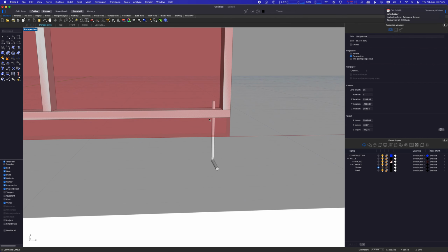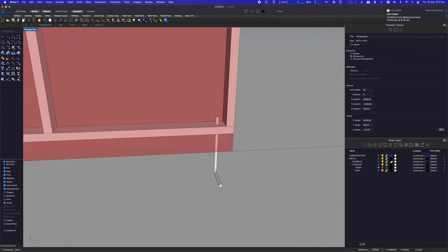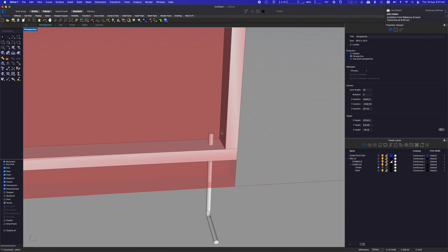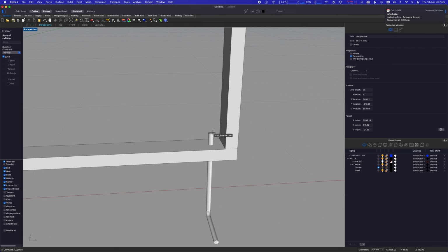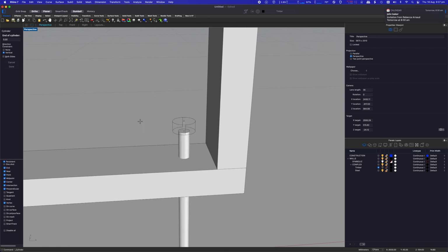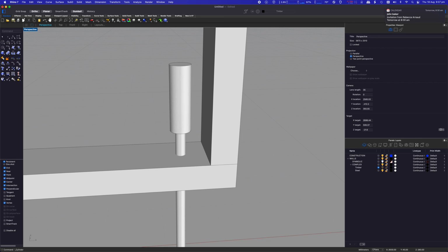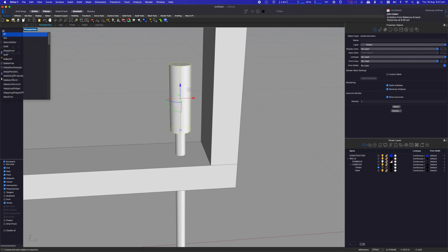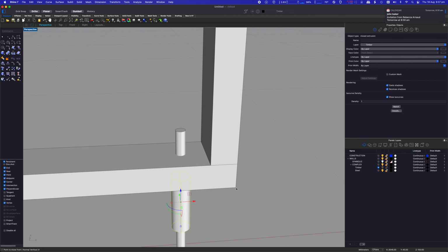So now we want the piece of 100 millimeter long 32 mil diameter tubing. So let's do a cylinder. Actually, let's just turn off the symbolic bit. Let's go from the center of there. We want, again, diameter 32, and we want it to be 100. Then we want to move that vertically from there to there.